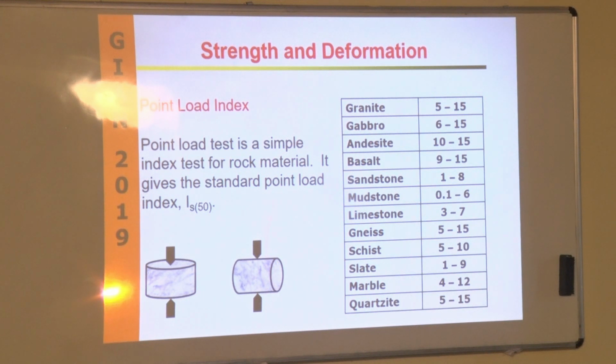That failure is then empirically correlated to everything, from porosity to strength, tensile strength, compressive strength. There is a joke in our lab that you can use the point load to do everything, even understand if it rains tomorrow or not, because there will be a correlation. So again, point load is a very useful test, especially because it's quick and can give you the range.